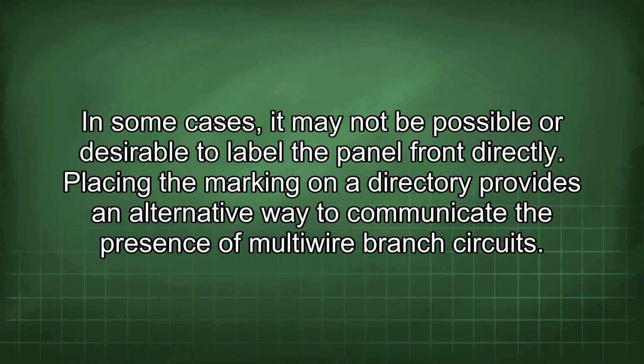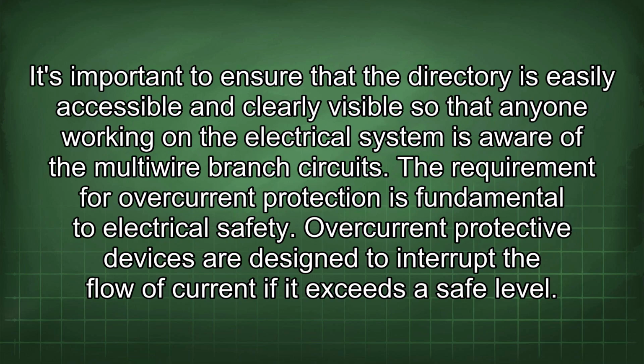Placing the marking on a directory provides an alternative way to communicate the presence of multi-wire branch circuits. It's important to ensure that the directory is easily accessible and clearly visible so that anyone working on the electrical system is aware of the multi-wire branch circuits.